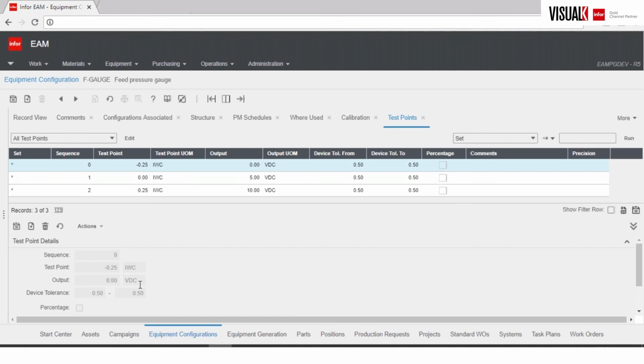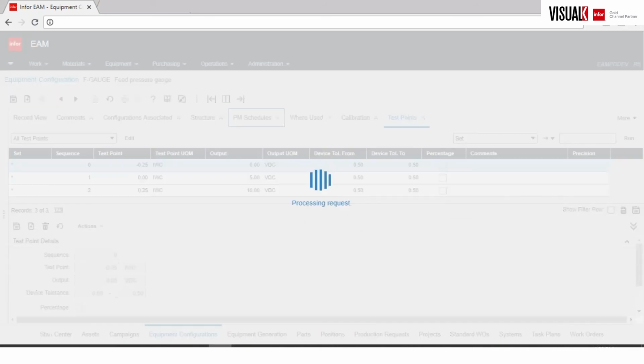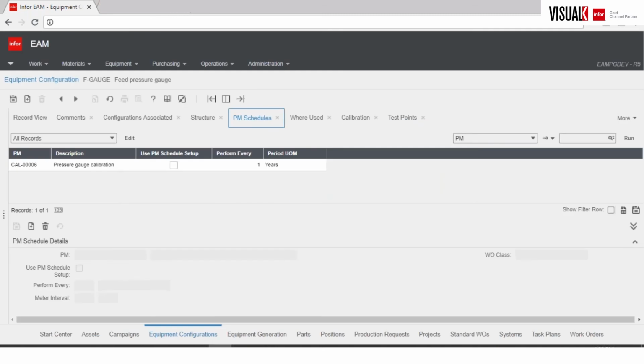And you'll see an example later. Obviously, the precision, if there is a P&ID, a process and instrumentation diagram, where this asset can be located, which one is it, right? And then I define my test points, right? So in this particular example, this would be my test point, so this would be my input, which would be inches water column, and then this will be my output.